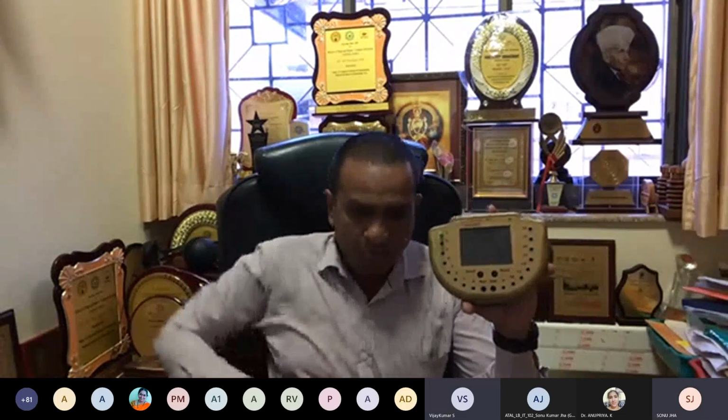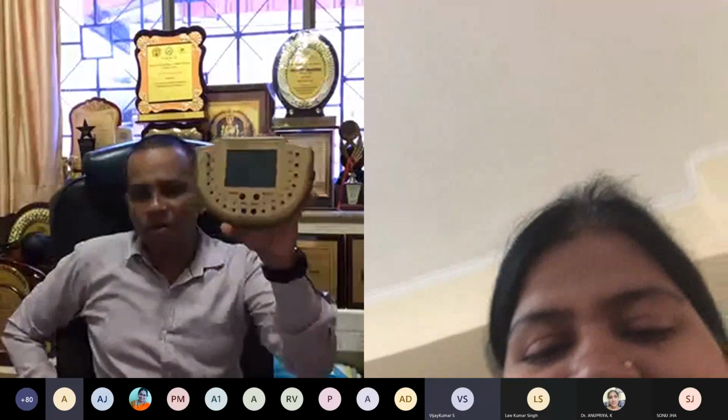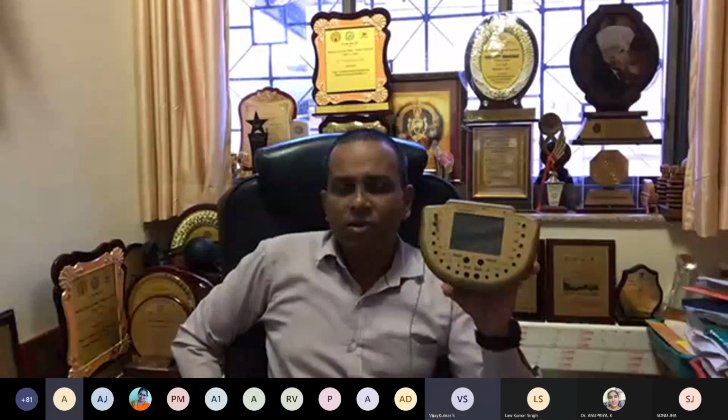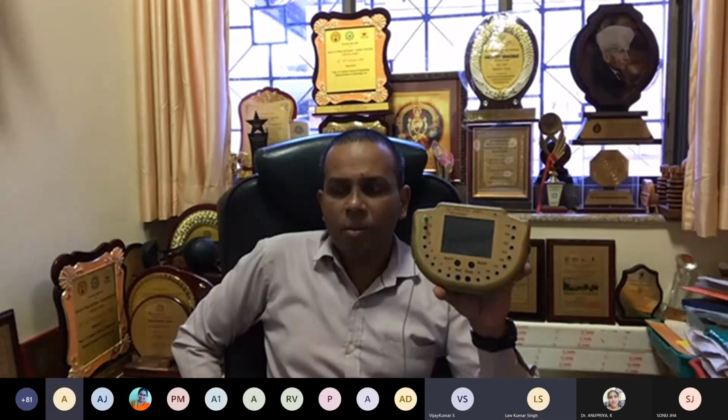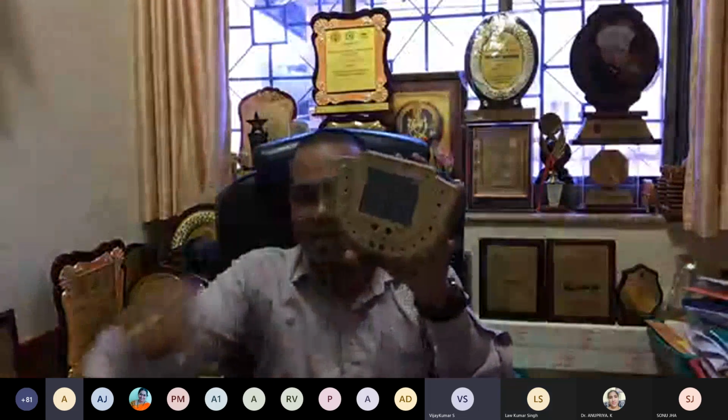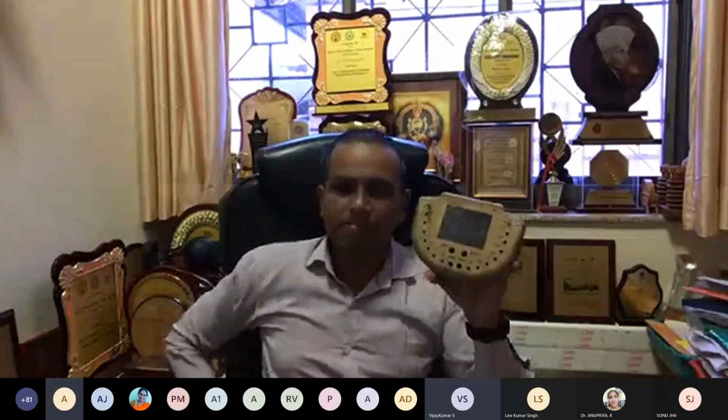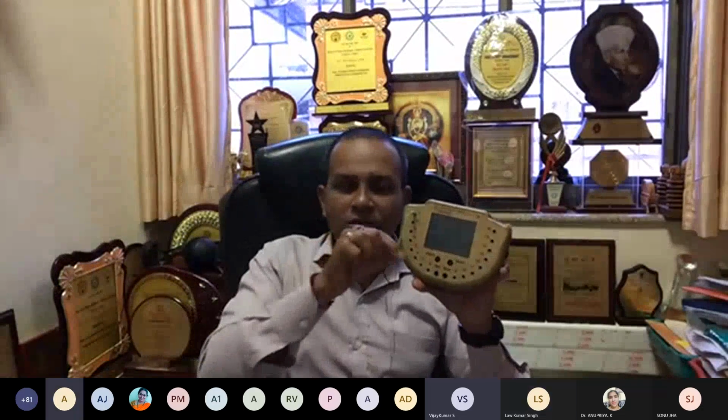Are ground and reference connected to the amplifier? Obviously. My question is, ground and reference channels are connected from the EEG cap to the amplifier? Obviously, otherwise there is no point. See, when you connect to the amplifier, if the other side is not connected, it will always record a zero signal. One side connected to the amplifier, the other side to the EEG cap.